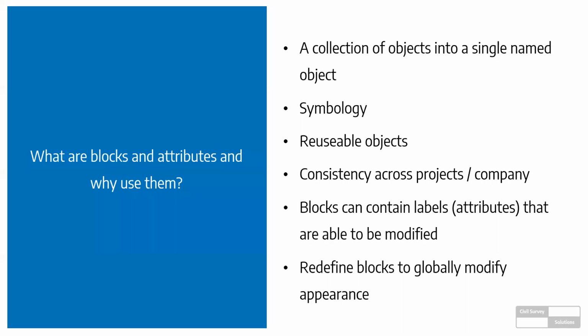information as well. We can create a block in a drawing, and we might find that we've created it with very, very simple symbology, just for the speed of the drawing to make it regenerate faster or something like that. You can actually go in and redefine a block and make the block more complex or simplify it even further. So you're not stuck with a block being created in your drawing and it's fixed as that particular block with the content that's in it. You can modify the blocks at any time.